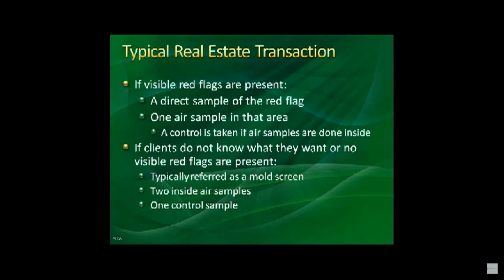If the clients do not know what they want, or there's no visible flags, they just want to say, we just want to know, is there a potential concern? It's called a mold screen. You take 2 inside samples in the common areas and 1 control outdoors. It's that simple.